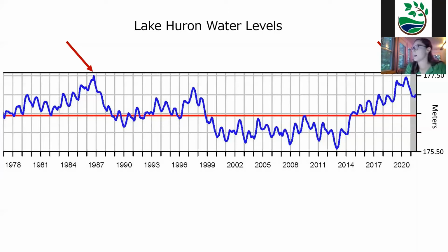And so really, once the toe or the bottom of the bluff is gone, the bluff is just waiting for those right soil moisture conditions to start failing. And so if you bought a property within this period of low water levels, you wouldn't have seen the cycles or all of the failures that happened in '87. So just be aware that it is a normal cycle of our lake, and it will continue to erode even just after water levels have declined.